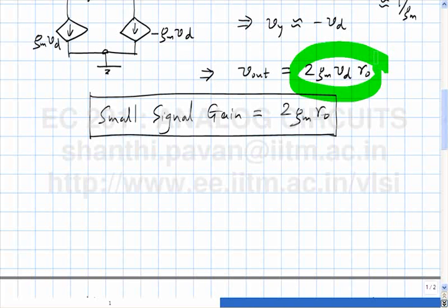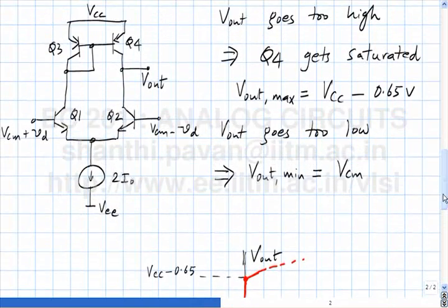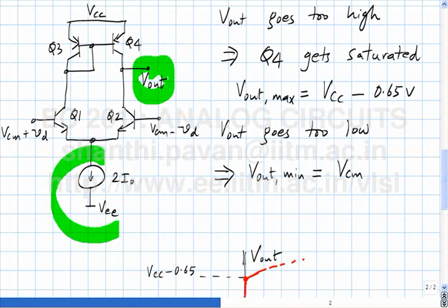In other words, the output of this amplifier, just like in the resistor case, is not sensitive to the common mode at all. This incremental output voltage only depends on the incremental differential voltage, because we have assumed that the output impedance of this current source is infinity.